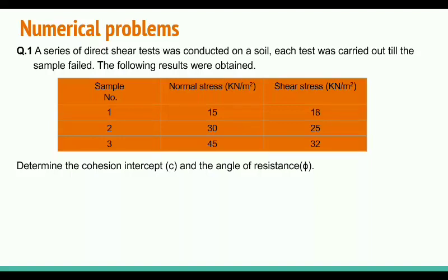See, this question you can solve by using graph paper. All these coordinates you have to draw on the graph paper, because the graph paper has proper scaling. So all the data is plotted with proper scaling. You can draw the x-axis, the sigma axis, and the y-axis, shear stress, that is the tau axis, and you can get the three coordinates.